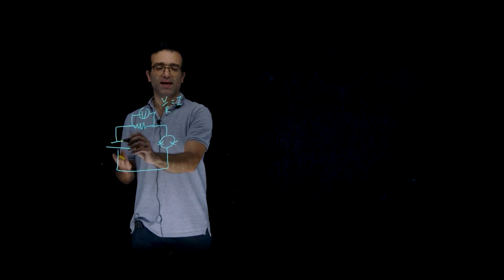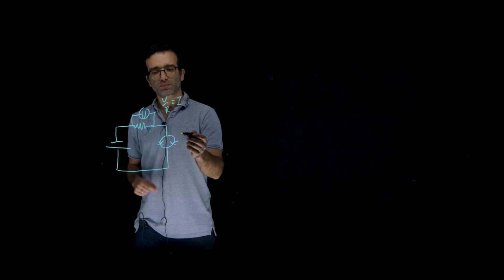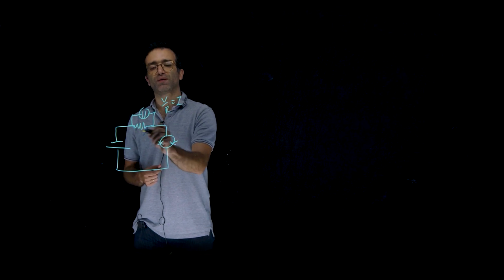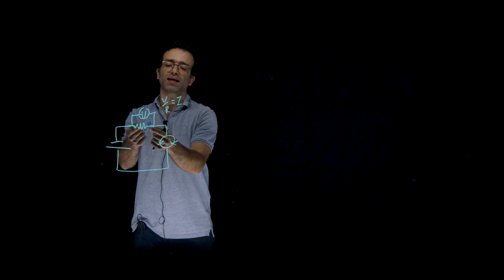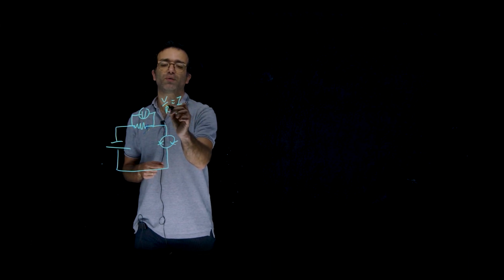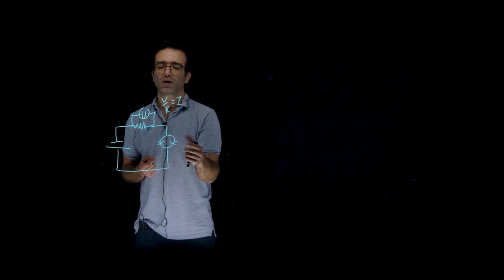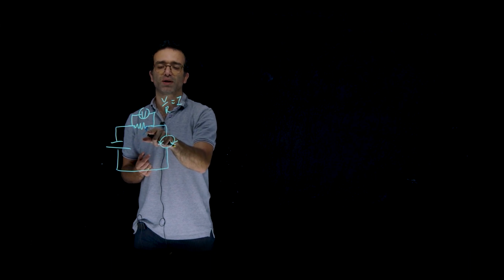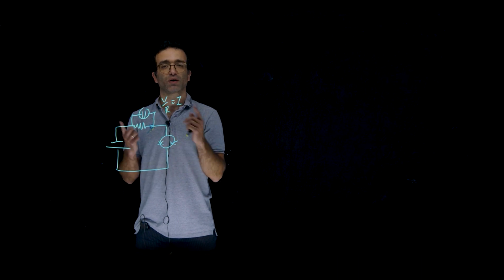And the voltage I set, and that's it. What is the problem here is that the smallest current is set by the value of this resistance. So if I have a very large resistor, I can measure very small currents. But if I have a very large resistor here, what I am essentially doing is a current bias and not a voltage bias.